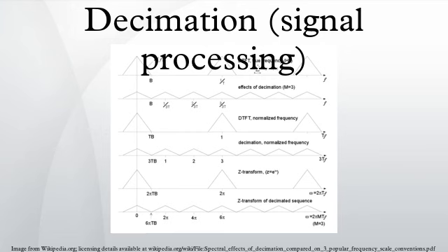In digital signal processing, decimation is the process of reducing the sampling rate of a signal. Complementary to interpolation, which increases sampling rate, it is a specific case of sample rate conversion in a multi-rate digital signal processing system. Decimation utilizes filtering to mitigate aliasing distortion, which can occur when simply downsampling a signal. A system component that performs decimation is called a decimator.